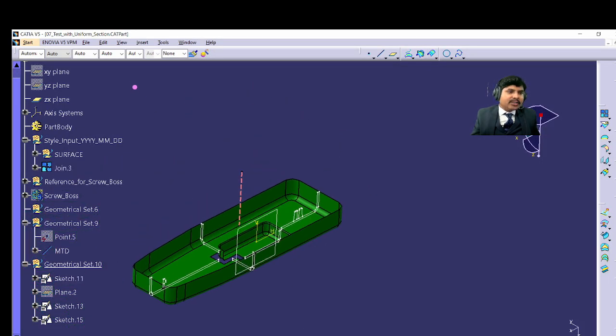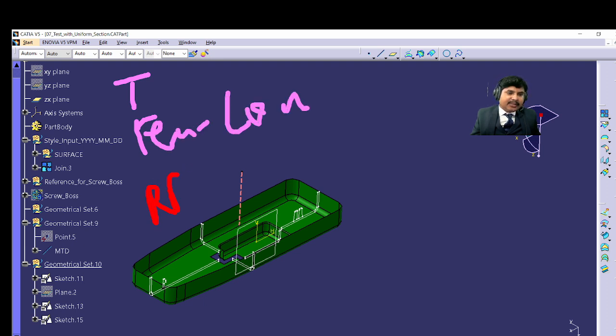In proposals what will be there? Size, length, width, height as I already explained. Then thickness is there. Then we have the features also. Feature locations depend upon the RPS, meaning reference position system, which is the degree of freedom. Then cutout is also there. Then we have to see the tooling requirements. Then we have to see the assembly requirements: two-way locator, four-way locator, gap, flush, clearance, each and everything.